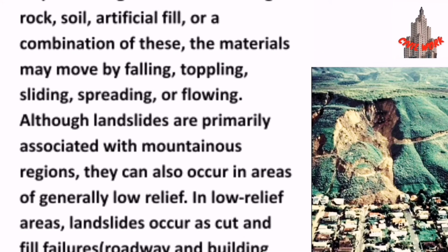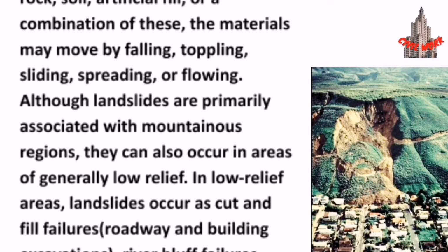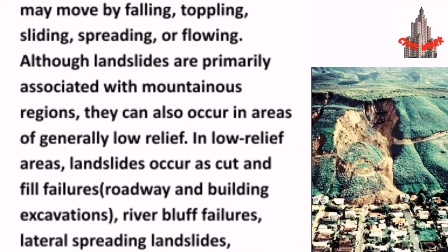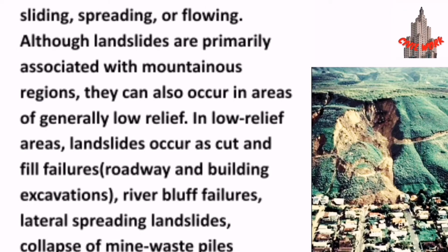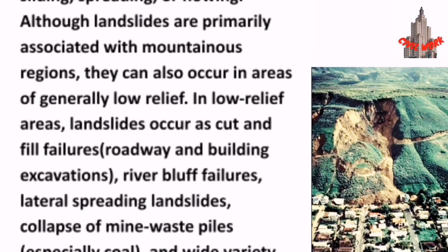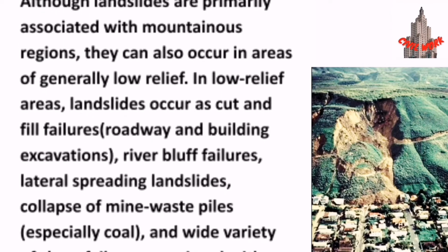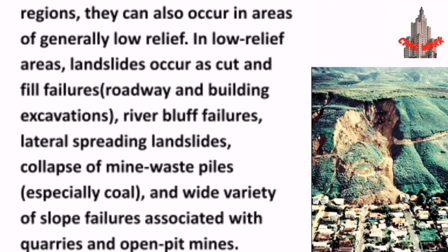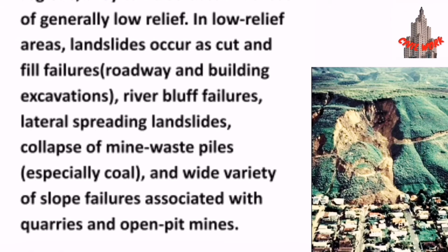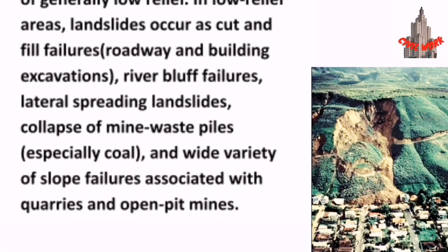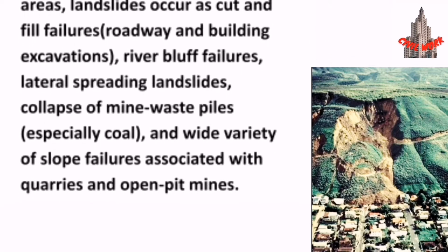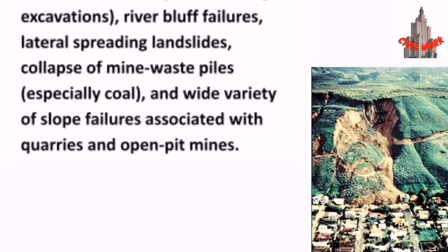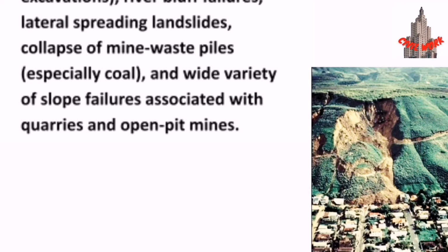Although landslides are primarily associated with mountainous regions, they can also occur in areas of generally low relief. In low relief areas, landslides occur as cut and fill failures, roadway and building excavations, river bluff failures, lateral spreading landslides, collapse of mine waste piles, especially coal, and a wide variety of slope failures associated with quarries and open pit mines.